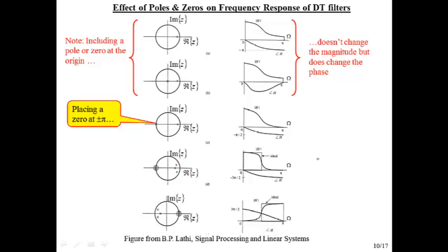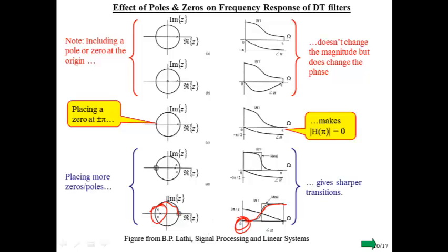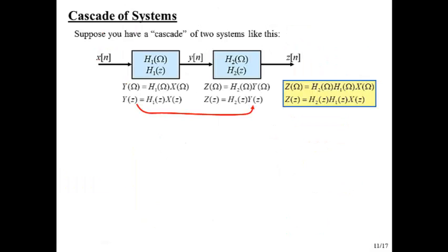Now if we want to make a reasonably good high-pass filter, well, now we put the zeros there. That's an angle of 0. So we're starting off at omega equal to 0, and as we walk around this unit circle from here, first we encounter the zero, so we start at 0, we walk around like this, and we start encountering poles, and so that makes us go up. But these things are structured in just the right way to make it level off flat. So that's a nice way of thinking about this. So you should practice this, and you can always check it out with Freq Z.